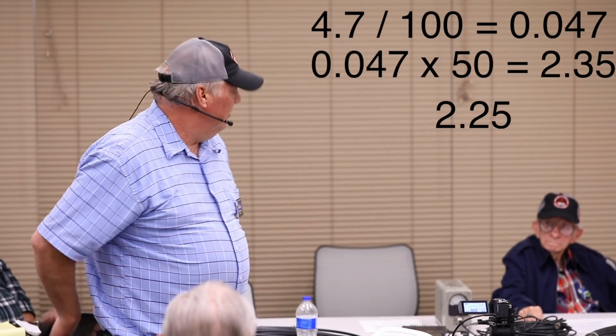So now, that's a 2-meter radio, and I put my 2-meter radio, and I got what was it? Did you write the number down? 2.2, 2.3 dB? Okay. So we lost 2.2 dB. What does that really mean? Well, it means my radio put out 42 watts, and my antenna that's resonant at that frequency is only getting 25 watts. You're almost 2.5 dB down, right?